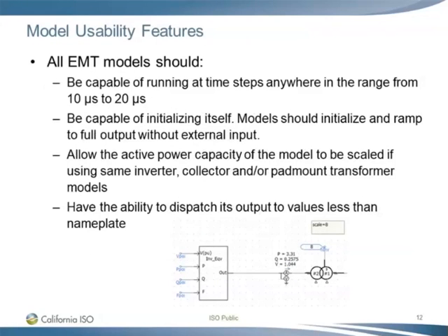Next, we'll cover model usability features. These requirements should be met for all EMT models regardless of generation type. All EMT models should be capable of running at time steps anywhere in the range from 10 microseconds to 20 microseconds. They should also be capable of initializing themselves.